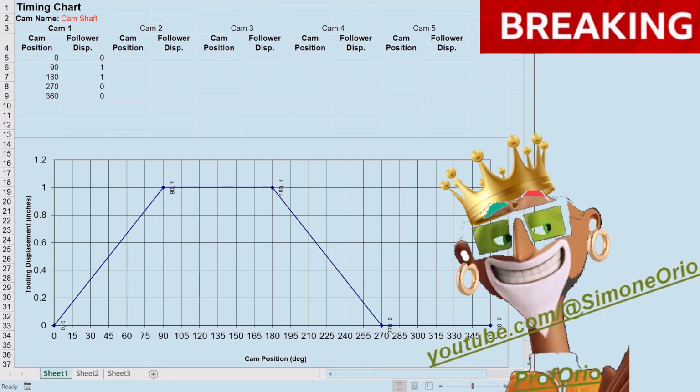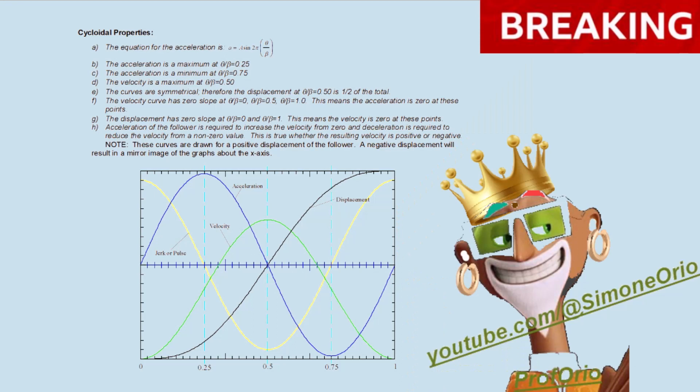In the timing diagram, all we have to show the motion are straight lines for the displacement rise and displacement fall. The next question is, what kind of motions do we want for these portions of rise and fall? This can be answered by looking into the available motions. In Cam Designer SE, there are the following motions available: cycloid,